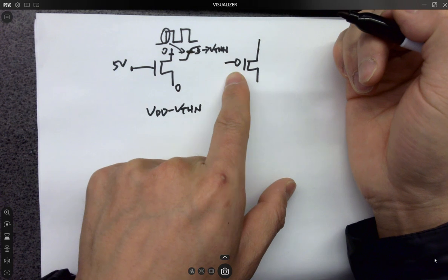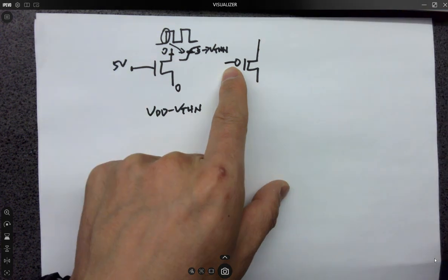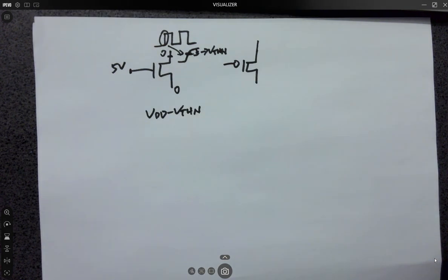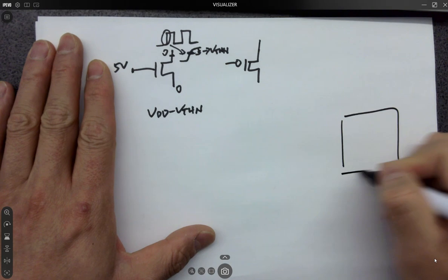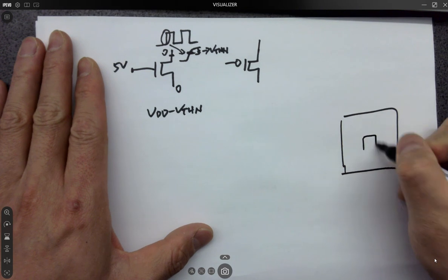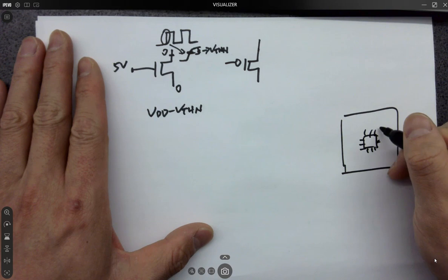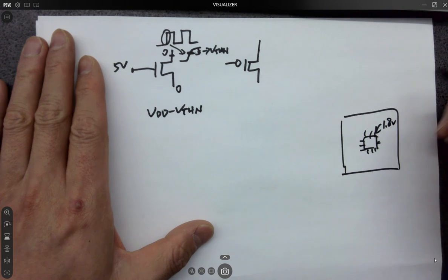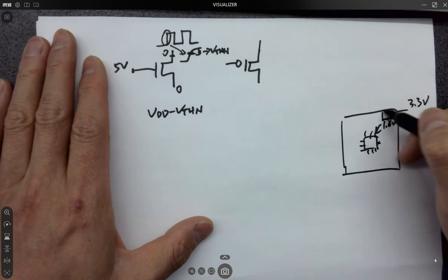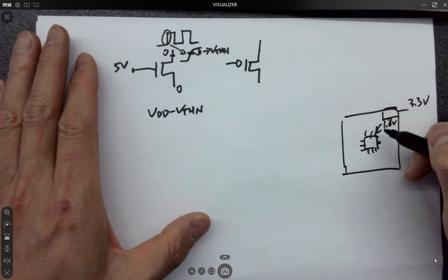you want to give what kind of voltage to the gate for PMOS? In digital signals, you don't have choices. There's not like 2 volts, 3 volts, right? It's just either ground or 5 volts, or logic 1. Doesn't matter. Sometimes logic 1 is 5 volts, sometimes it's 3.3 volts. And for all these low power designs, even for the 180, the core in the chip usually takes in 1.8 volts as VDD. However, your power supply is still 3.3 volts, so there's a voltage regulator inside the chip to step it down to 1.8 volts to supply power to the core.